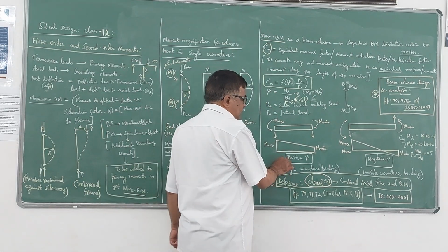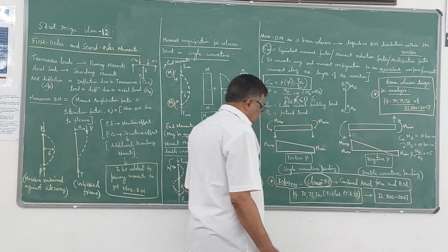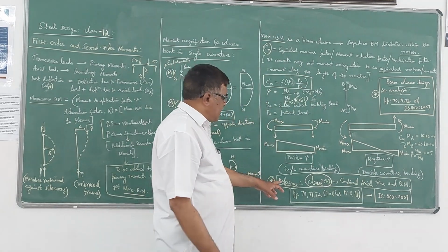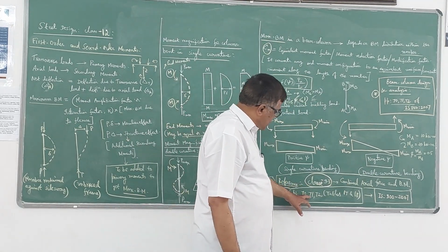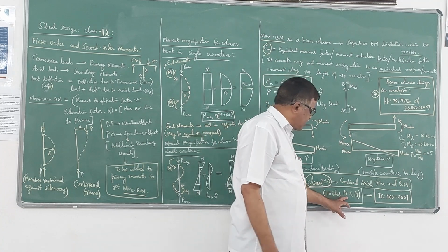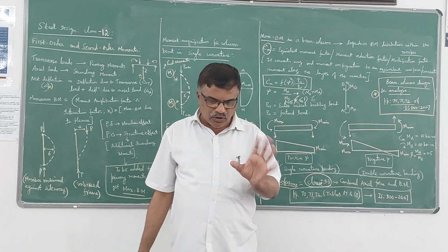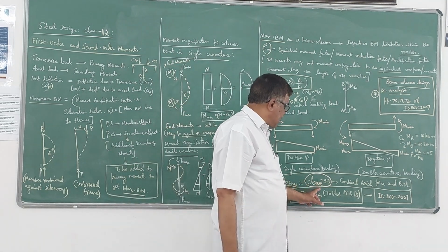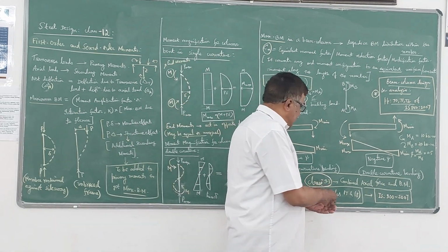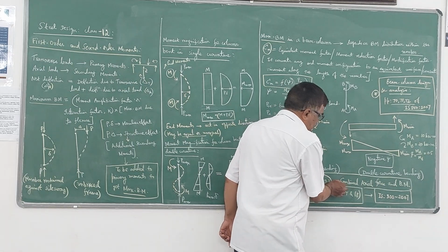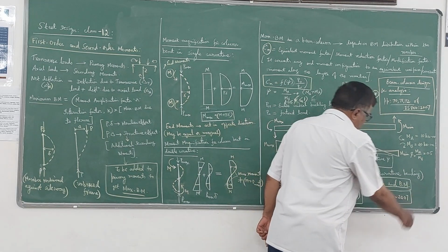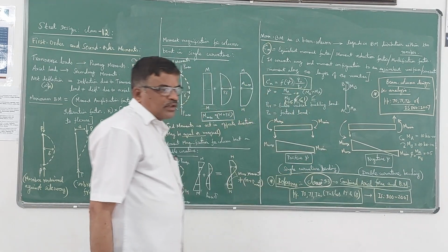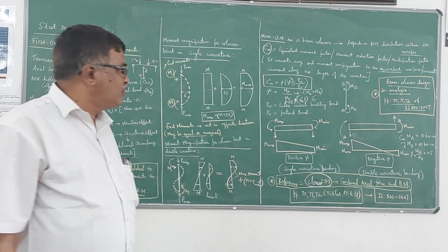So one is single curvature bending, another is double curvature bending. You have to refer to page numbers 70, 71, 72, tables 17 and 18, which are given in those pages only, for the design of beam columns, and it is in clause 9.3. It is written as combined axial force and bending moment. So these are the pages we have to use for the design of beam columns.